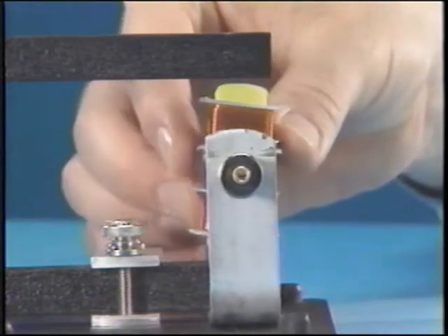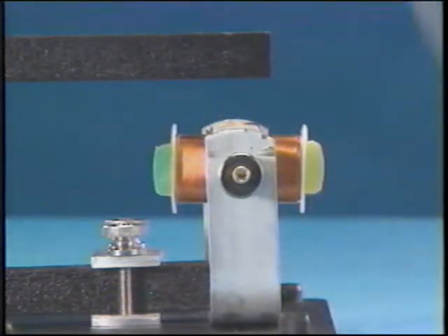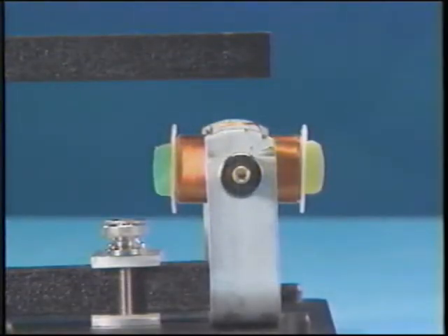As the coil rotates further, it moves back into a horizontal position. As it does, the coil cuts fewer and fewer flux lines. Once again, when the coil reaches a position that is parallel to the magnetic lines of force, no voltage is induced because, for this instant, no flux lines are being cut. But notice at this point that the coil has rotated 180 degrees, or a half circle, from where it started. Now the yellow end is on the right and the green on the left.